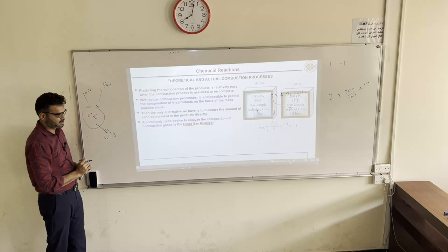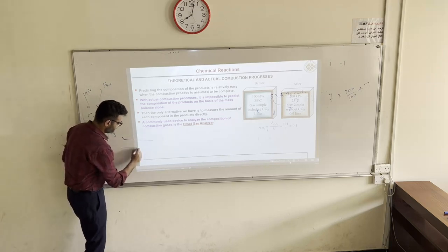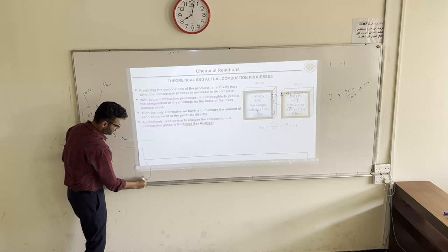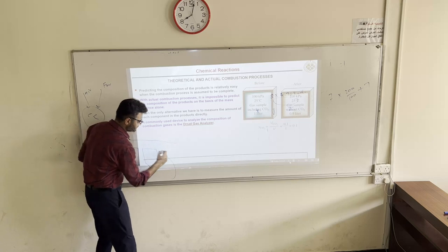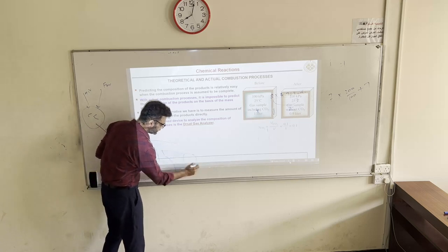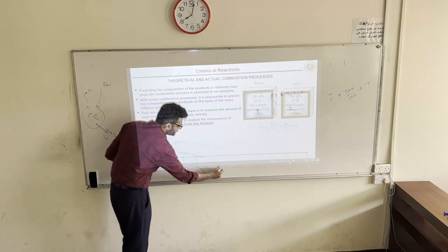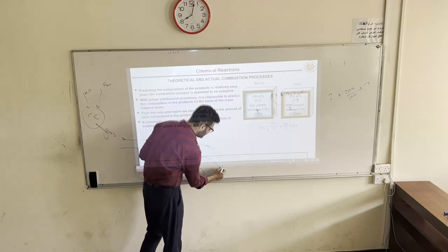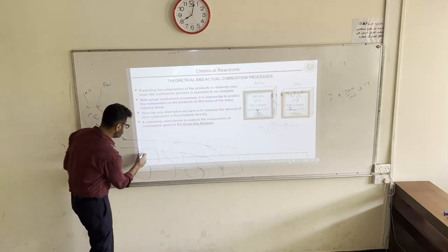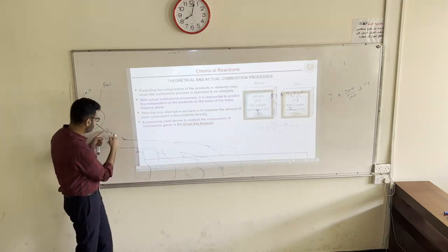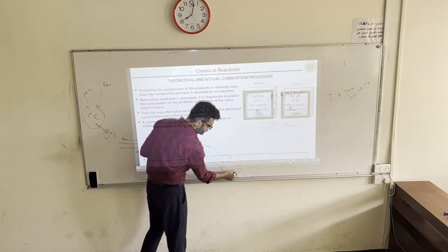Now you make these exhaust gases flow into this Orsat gas analyzer. In this Orsat gas analyzer, if I remember correctly, there are a number of vessels with different chemicals in them. And here you have some water tank. Initially those are closed. So this gas will continue to flow here in this water column.